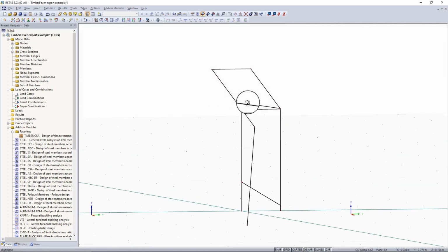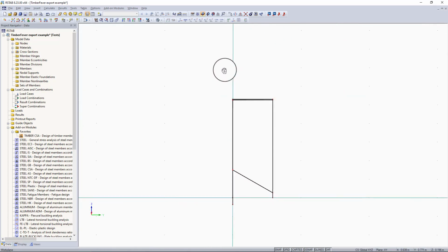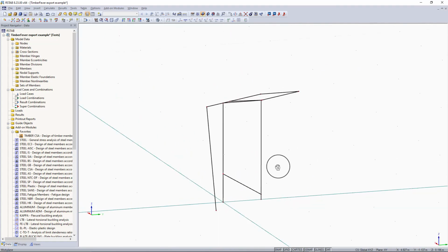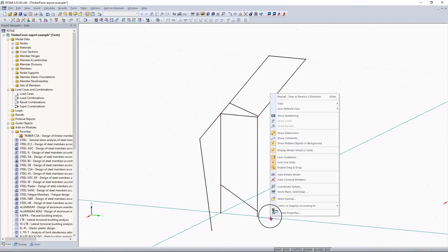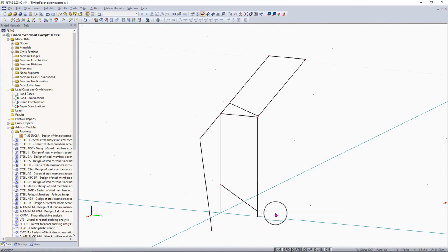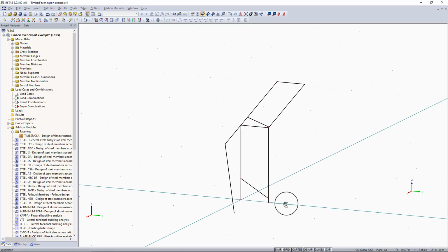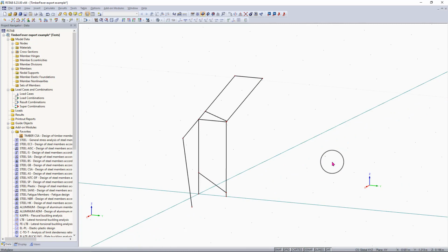So I know that seemed probably like a lot of work just to get these lines connected, but it definitely makes the rest of this modeling a lot easier. Because now what we can do is simply mirror this whole thing, copy it, make copies of these lines here, mirror this frame here, and then copy, and you'll see that we'll have the rest of our structure created.